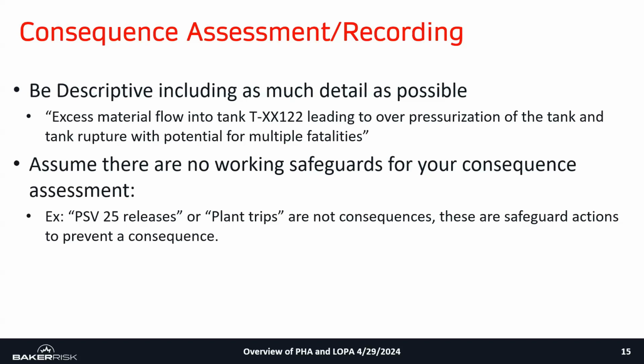One key philosophy to keep in mind is when you're defining the consequence in the PHA, you basically assume that your safeguards do not work. So that's a very important nuance for the PHA team to remember: assume when you develop your consequence, your safeguards aren't functioning.